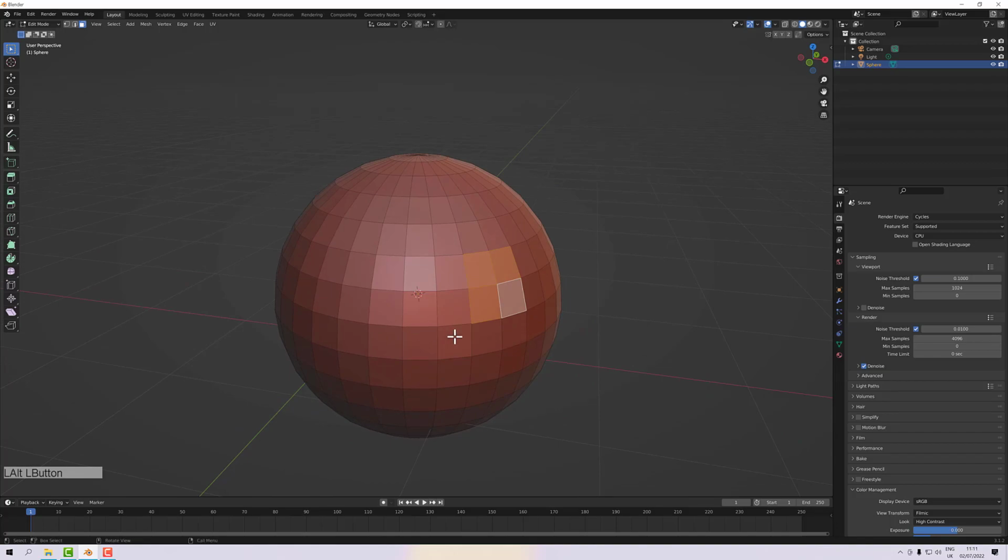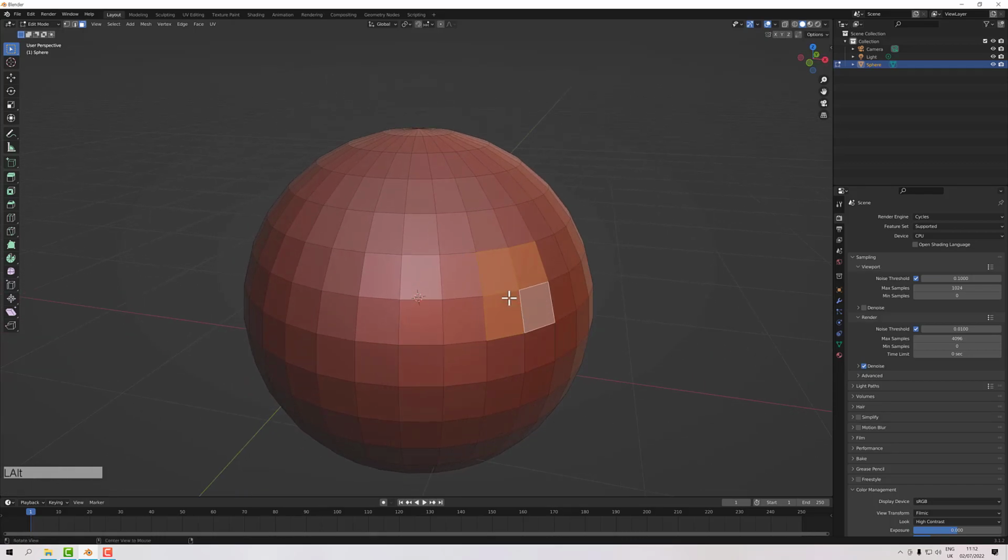So if I press the S key, it will scale what I have selected, and it will scale it according to your camera angle, and also according to how far you move your mouse. You see I've got this little arrow and this dark line. That's giving me a visual idea of whether I'm going up, down or otherwise. So again, if I just press the Z key, it's only going to go in the Z axis, the Y key, the Y axis, and the X key, the X axis. And right click will send me back right to where I started.